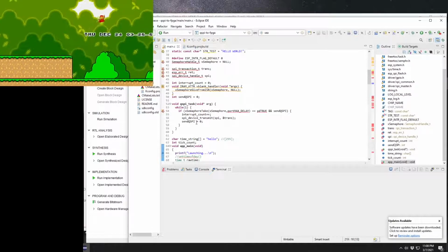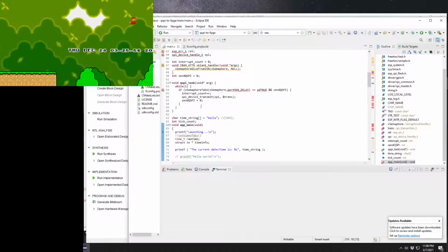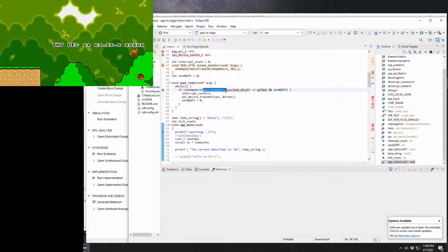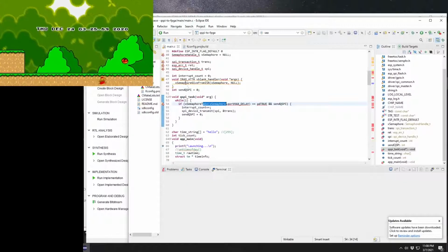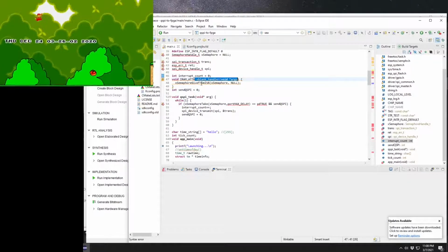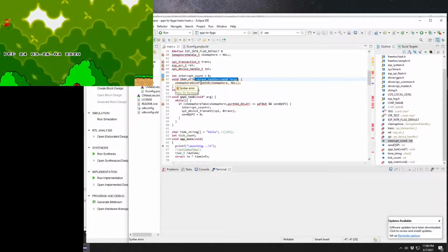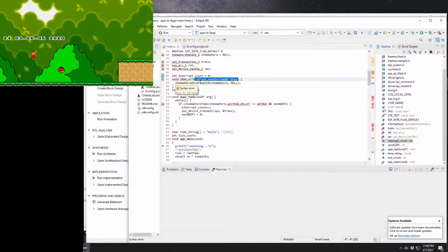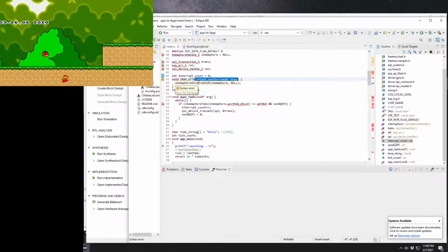As soon as we get the signal that we're in that blanking period, we have the interrupt set up here. That interrupt is a vBlank handler. It's tied to a specific GPIO pin, which is connected between the ESP32 and the FPGA.